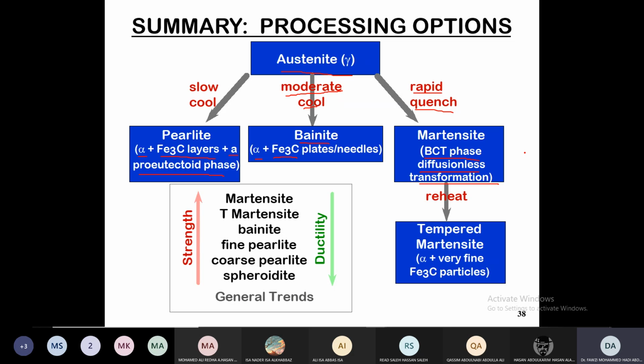Suppressing. Why? With this very fast cooling or quenching, you suppress the diffusion process and trap the carbon atoms inside the BCC crystal structure. But since it cannot accommodate that many carbon atoms, it causes twisting and elongation of the BCC crystal structure, forming that BCT crystal structure.